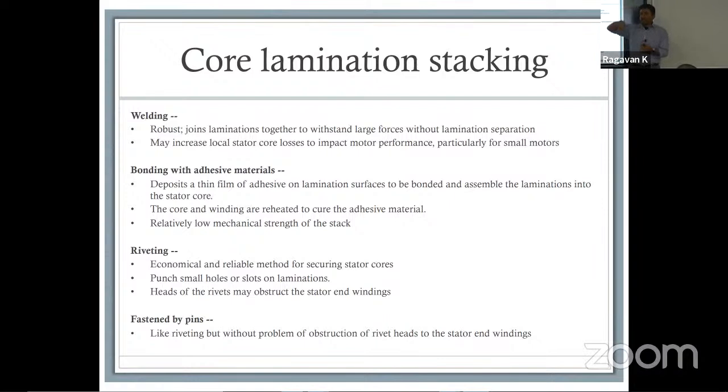You can either weld them together. Make sure you're not welding the high field components. You created laminations for eddy currents. Don't weld them, because if you weld the parts that you laminated, you just created a path for it to close again. You can bond with adhesive material.